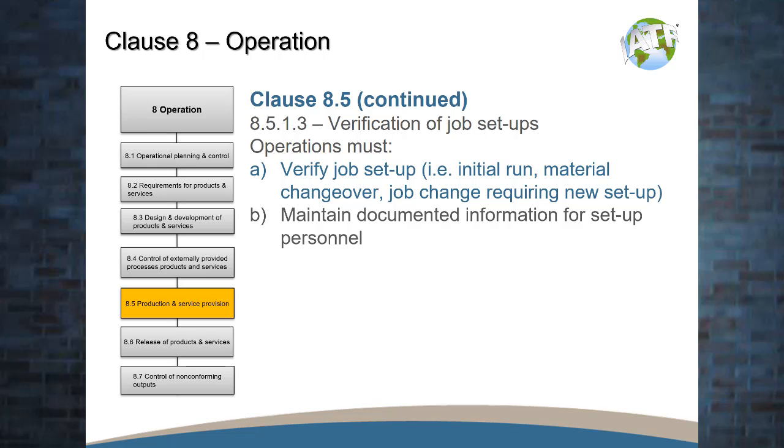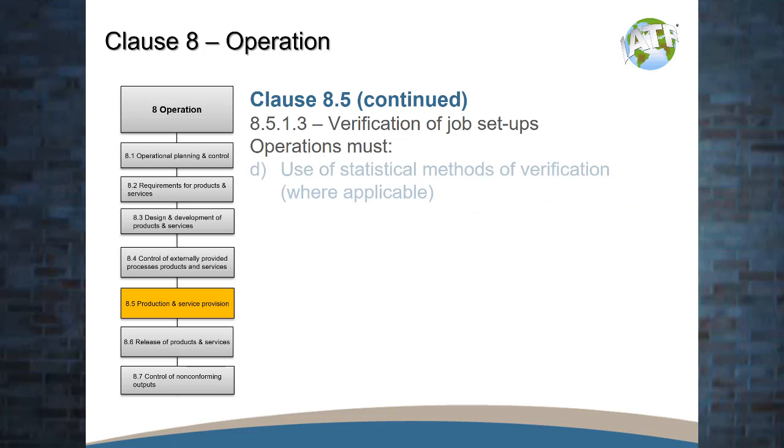B here, maintain documented information for setup personnel. So the idea here is you need to keep up and have a documented procedure, standard work instruction, some sort of documented information for those folks that are responsible for setting up the production or the service provision there. Also, use of statistical methods of verification where applicable. So when you can use statistical methods to verify proper setup, you should do so.